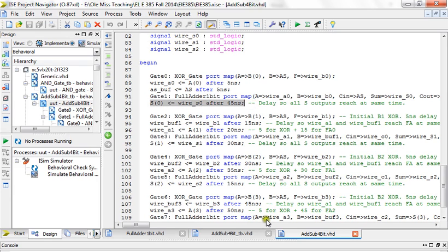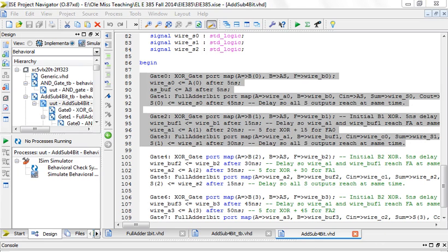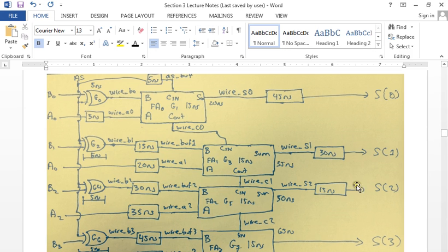I can do that. So what you would do if we wanted to reduce this, I would do this, and then just put two full adders together where you're just controlling the timing of the inputs and the outputs to make sure they match. So if I was doing a 32-bit value, we could actually do the quick math. Each one's going to be 20, it's going to be 5 plus 32 times 15. So that's going to be our last value. So each one's going to subtract 15 the amount of delay.